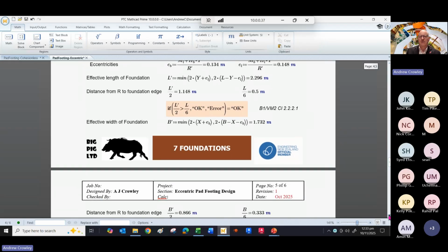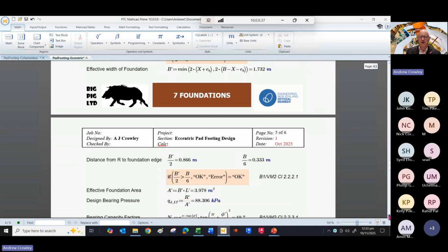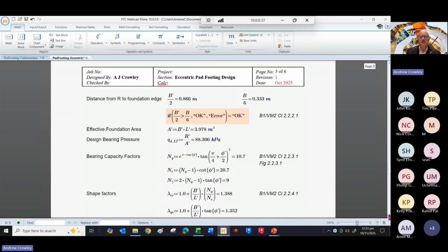Now, because the depth of the groundwater isn't particularly deep, the figures are not hugely different. However, if you have a much deeper foundation with a much greater height of groundwater, then there can be a big difference. And if it's deep enough, you might even get uplift from buoyancy.